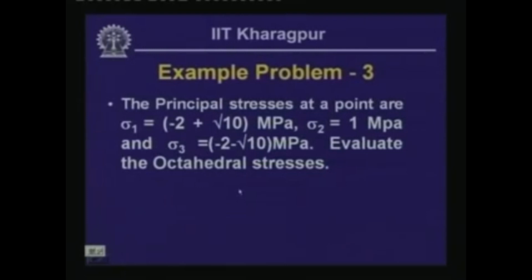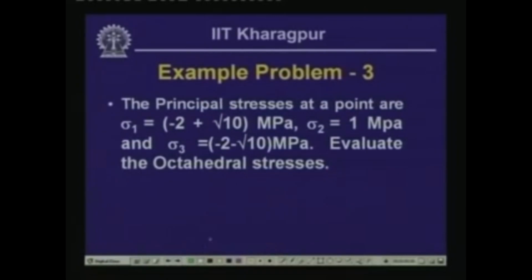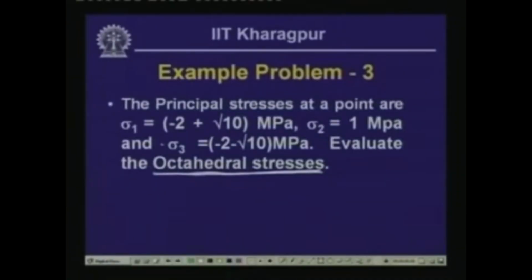Now, let us look into another problem, wherein we had last time discussed the values of the octahedral stresses. As I have told you in the beginning, octahedral stresses are the stresses which act on the octahedral plane, and octahedral planes are the planes which are equally inclined with respect to the principal axis, the sigma 1, sigma 2, sigma 3 axis system.